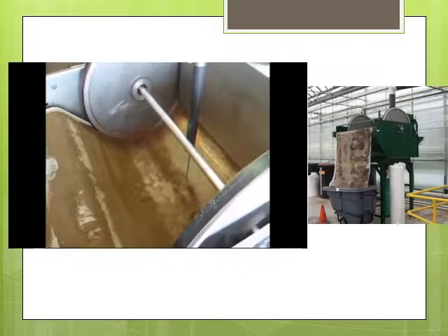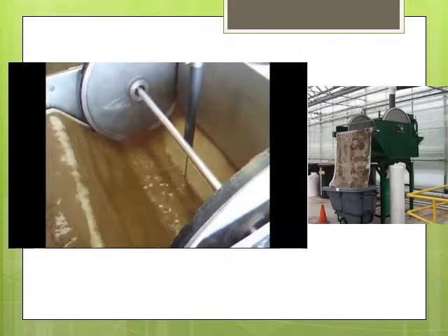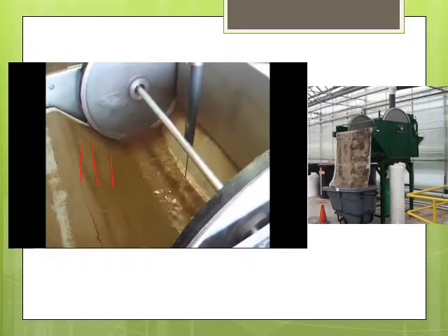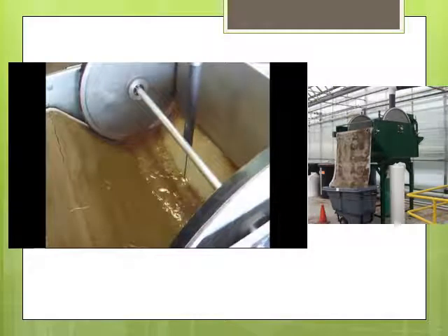Here you can see the water is coming in, and it's got lots of sand, and the sand is getting caught on the paper. The way it works is that this probe right here, when the water starts to back up into this valley and gets high, it touches the probe, and then it triggers these wheels to rotate, and they pull fresh paper down into the valley. And so the dirty paper comes out the other side and is collected as waste.